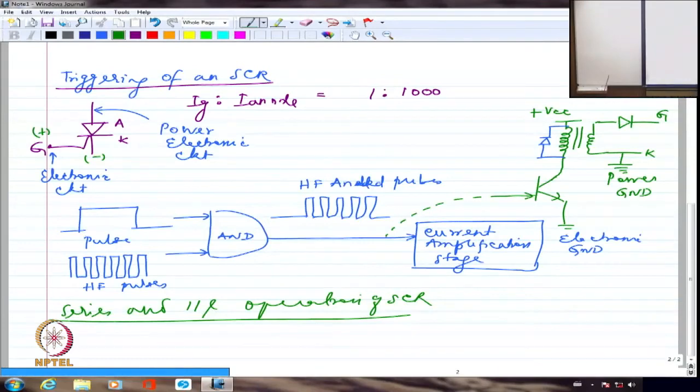See, you are doing the power amplification. This is even power amplifier. I should not say only current amplification. It is actually power amplifier. Because what I get from here may be 5 volts, and what I get from here may be 15 volts, and what I get from here may be milliamperes or microamperes, but what I get from here will be of the order of amperes. So I'm not only amplifying only the current, I'm also amplifying the overall power, and for that I'm drawing the power from VCC. So VCC is supplying the power for me to amplify the current pulse.